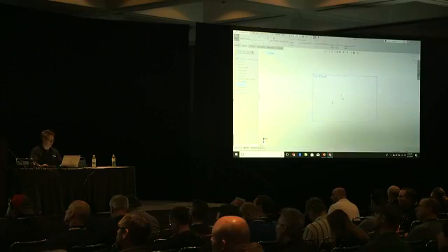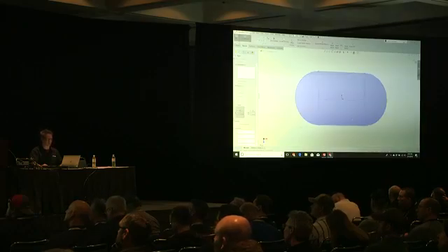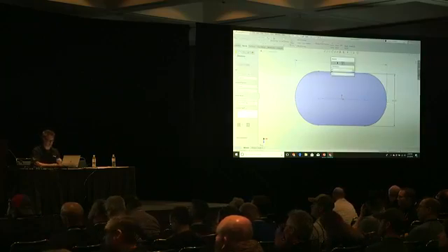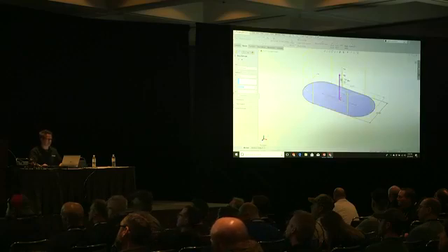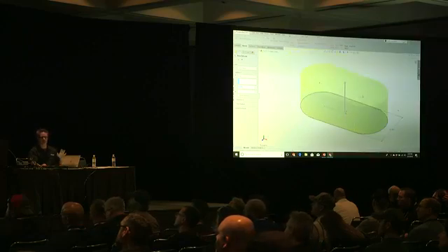Top plane. A lot of people don't think of the slot as a tool for drawing things other than slots. It works great for drawing other stuff as well that might have that shape. In case you don't know this, when you dimension, you can grab the outside by holding shift. That's one that I always throw out there because there's people that don't know. I like to help them out. I'm going to drag it up, get closer to this, and it snaps to it. Let's go about 18. Looks like a comfy tub, right?